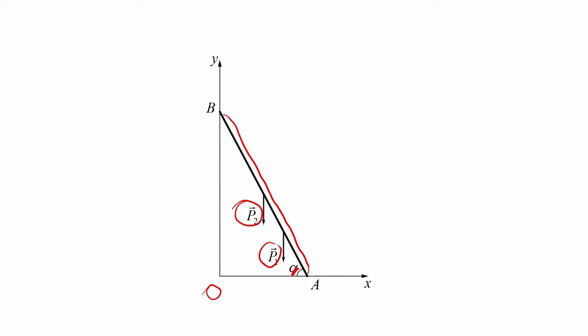The equilibrium condition for a body with the presence of slide and friction can be articulated as follows. The reaction of a rough surface must be passing inside the friction cone. In our case, we have two rough surfaces, the floor and the wall, and so we have two reaction forces. To build a friction cone and use it for solving our problem with the equilibrium condition, we are to utilize the coefficients of friction, which are directly related to the friction angles.